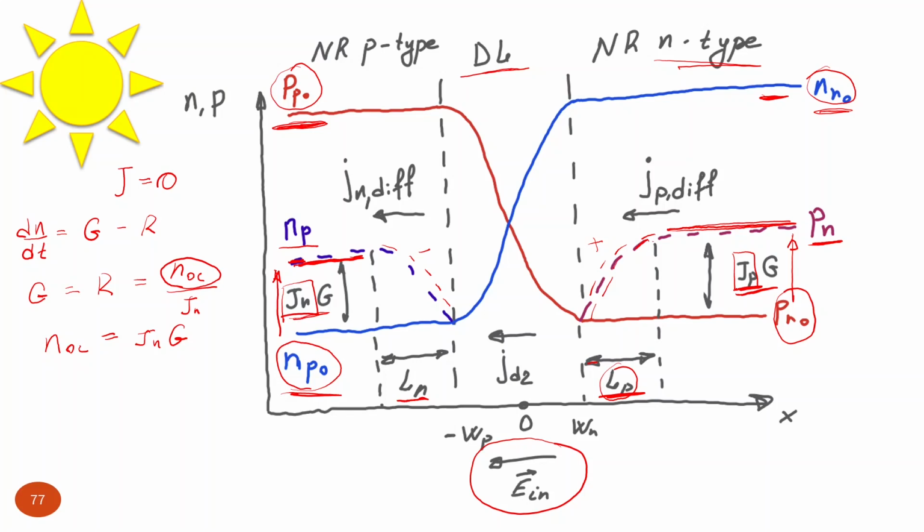So obviously, if we go further from the edge of the p-n junction into the neutral region, they cannot come from here to here, because the distance is too big, they will recombine on the way. So this electric field, which extracts charge carriers, will not have impact on the charge carrier concentration profile deeper in the neutral region than this diffusion length Lp. And the same for electrons, but Ln. So this diffusion length is kind of a dead zone, yeah?